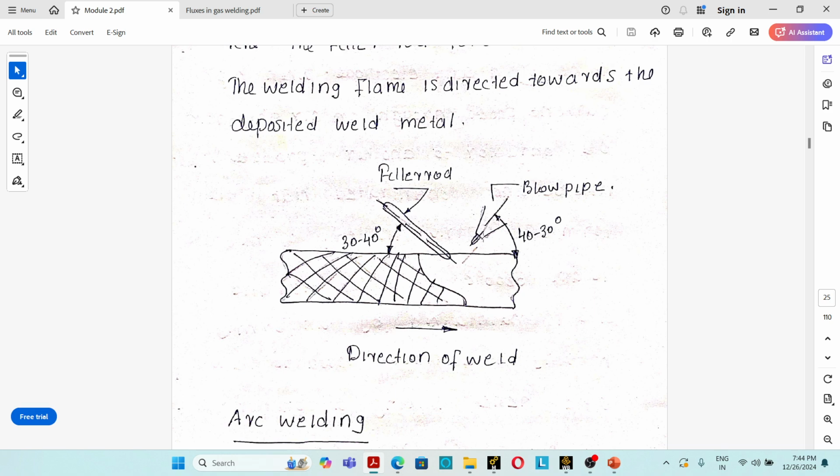This right hand welding technique has one importance. It is used to weld thick steel plate above 5 mm. In the welding process of steel shells, the right hand welding technique is also used. So these are the two welding techniques in the oxy-acetylene welding process: the leftward, forehand or forward welding technique, and the rightward, backhand or backward welding technique.